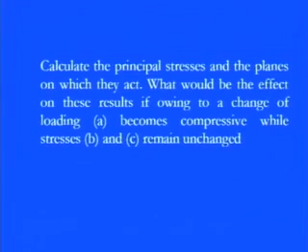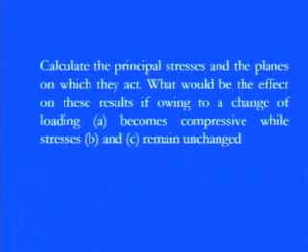Now the calculation part is to calculate the principal stresses, because all three types of stresses are there. We need to calculate the sigma 1 and sigma 2 values, the maximum and minimum principal stresses, and also the location of the principal planes at which they act, and what would be the effect on these results if, owing to a change of loading, A becomes compressive.